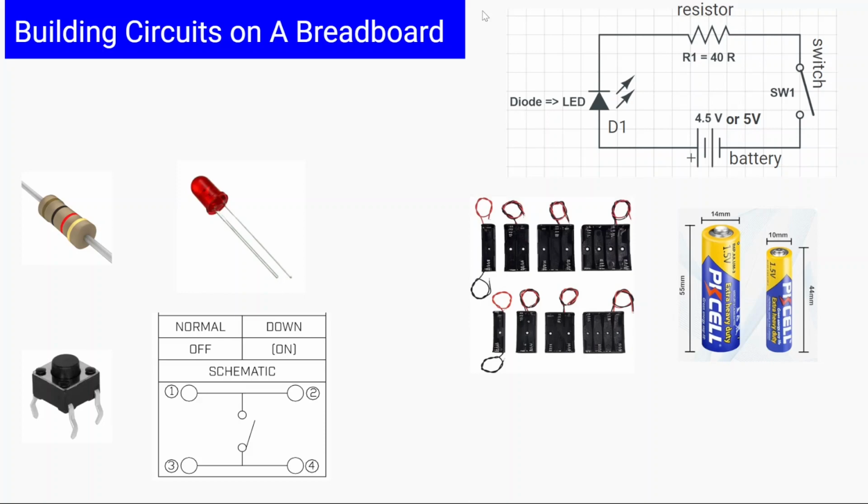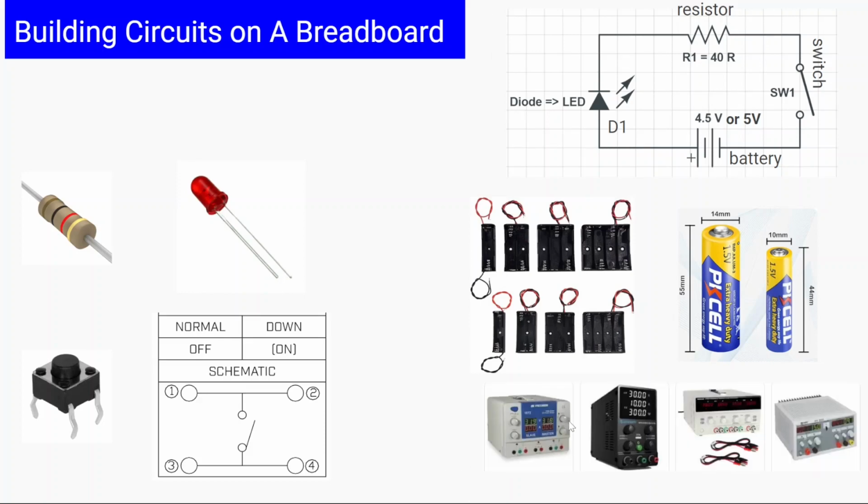So let's go to the power supplies. As mentioned here, you can find these power supplies inside the lab, and red means plus side, and negative most of the time is black, but on some power supplies you will see a yellow terminal as well. The yellow means the negative voltage. Like here you can see, and similarly here I think it has a negative, because it has 3 terminals as you can see here. So it has a negative voltage side as well. It means that most of the time we'll be only working with plus and ground. Okay.